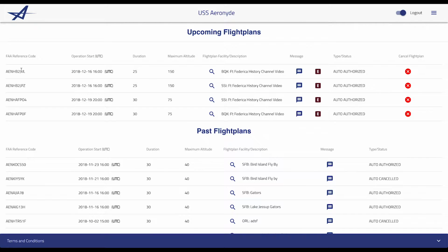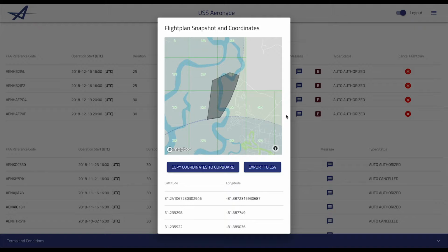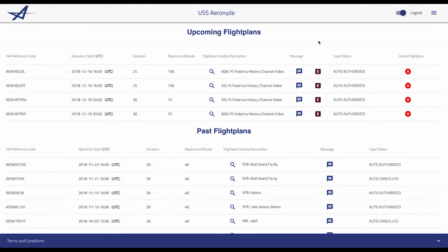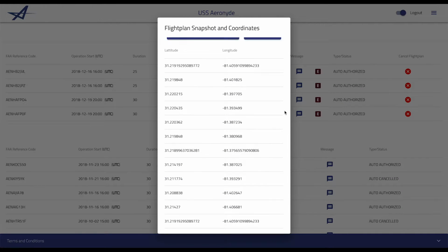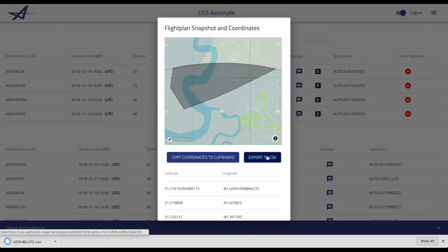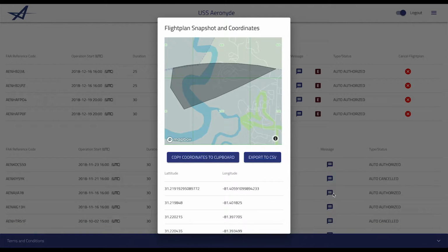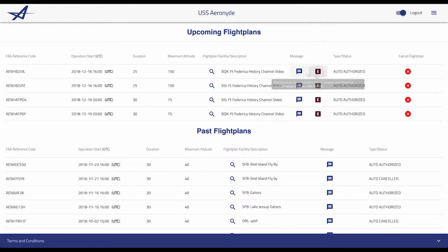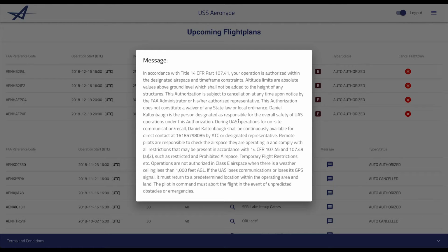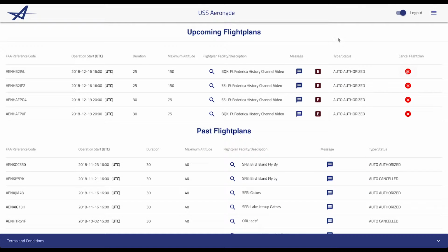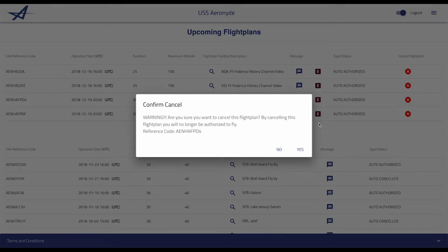Fortunately, in this case, the FAA allows any operations in controlled airspace that meet all the requirements to be automatically approved. You can see on the dashboard that we have the area of operations along with coordinates for the two parts of the operation. Operations at this time are limited to one per controlling facility, such as an airport. Since our total operation area encapsulated two controlling facilities, there are two operation entries. Each one has its own operation code.